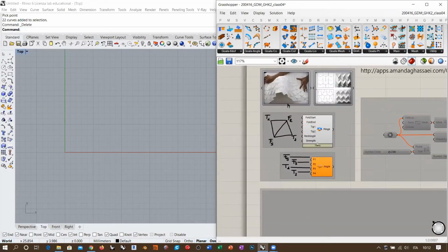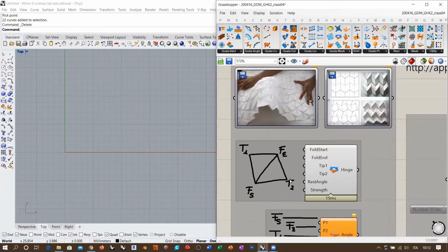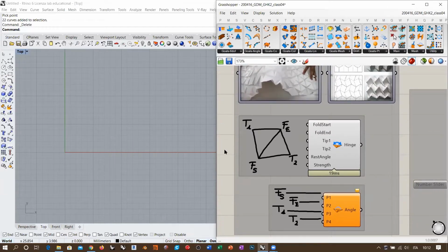So first of all, I wanted to point out how origami structures work. Normally, and especially with Kangaroo 2, I told you that today we are also going to introduce some workflow with Kangaroo 099, because Kangaroo 099 has a different approach to origami than Kangaroo 2. With Kangaroo 2, it's as if it has been somehow simplified for the masses, okay? Because as it has become very popular, probably there was this kind of simplification in its behavior. But we will see that Kangaroo 099 allows you to do complex things more easily if you know how to handle it, okay?